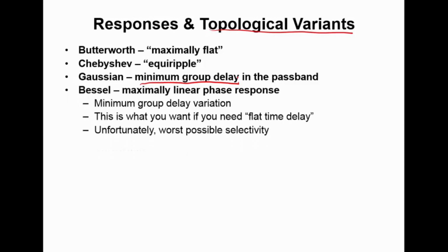The Bessel response, you explicitly try to make the filter have linear phase response. So that means this is the filter response that will give you the minimum group delay variation. And this is what you want if you need flat time delay. And RF engineers use this term quite a bit. Flat time delay simply means no dispersion, minimum distortion in phase versus frequency.